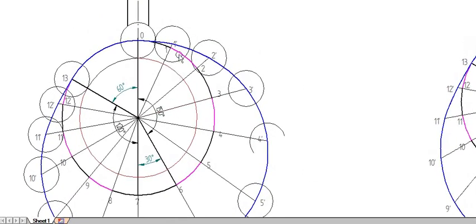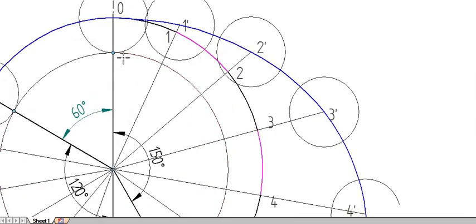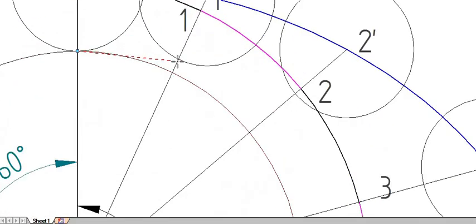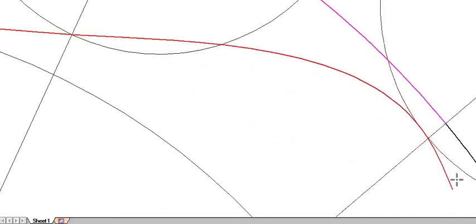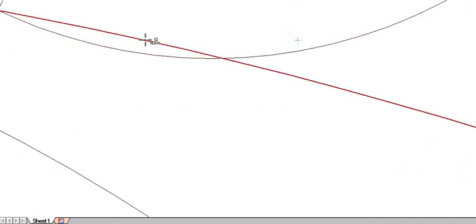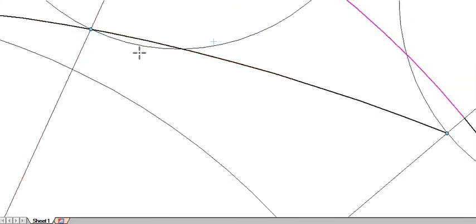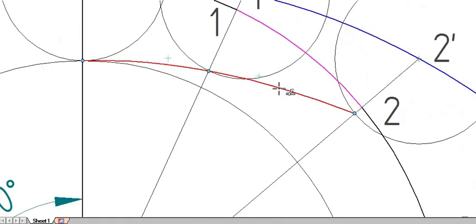After drawing the circle, connect a curve which runs smooth onto the roller. So I am connecting a curve. You cannot select the intersection point. If you select the intersection point, as I have selected here, the curve passes over the roller. That is not possible. You have to pass the curve at the bottom of the roller, as a smooth curve.